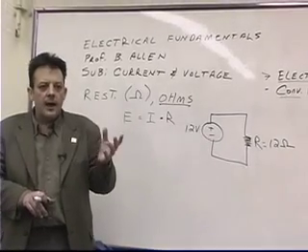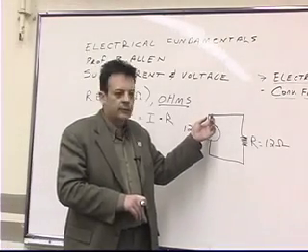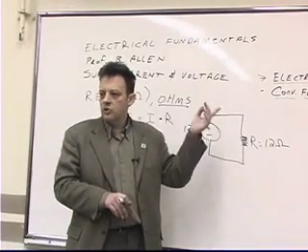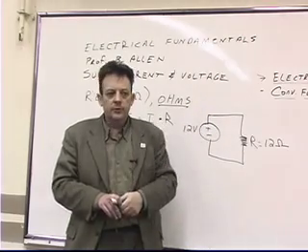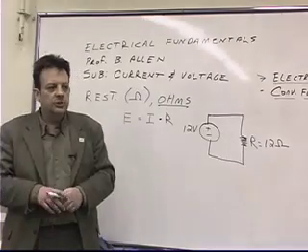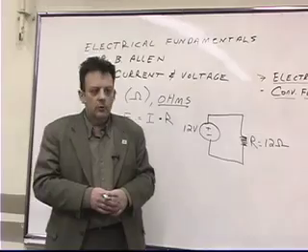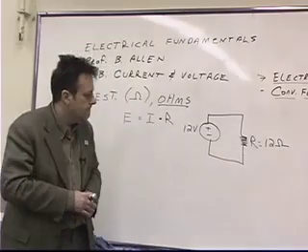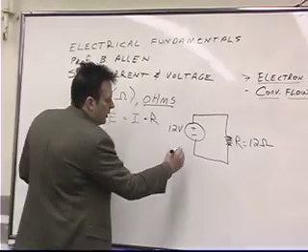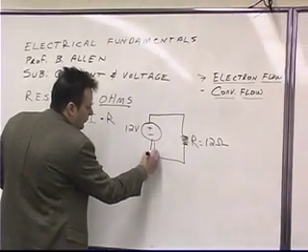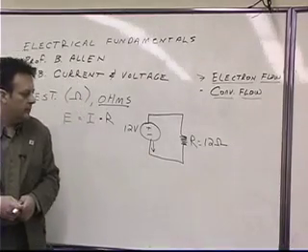With a little bit of math, in other words, all they have to say is, yeah, that's a negative current, which changes the direction of the arrow. Okay? So it's not that they're wrong, it's just a tradition. It's been handed down for over 100 years. Okay? Now, using electron flow theory, we know that the electrons are going to flow out of the negative terminal of the battery. Okay?